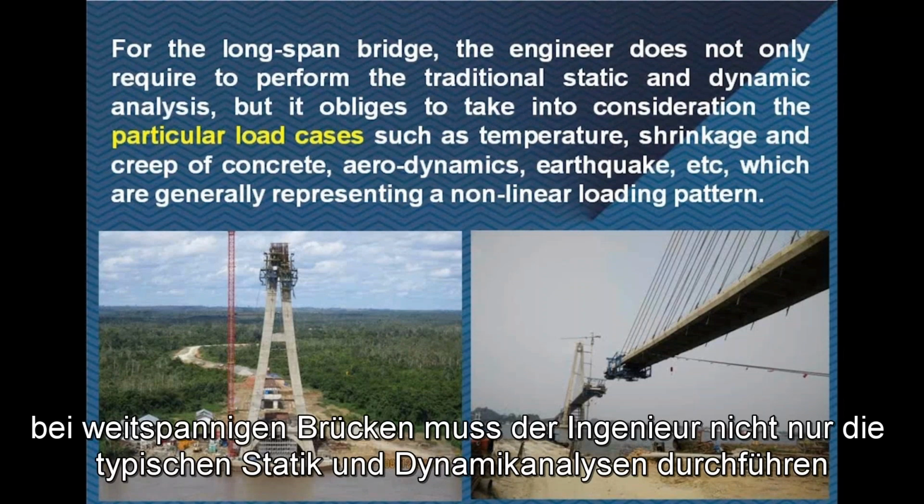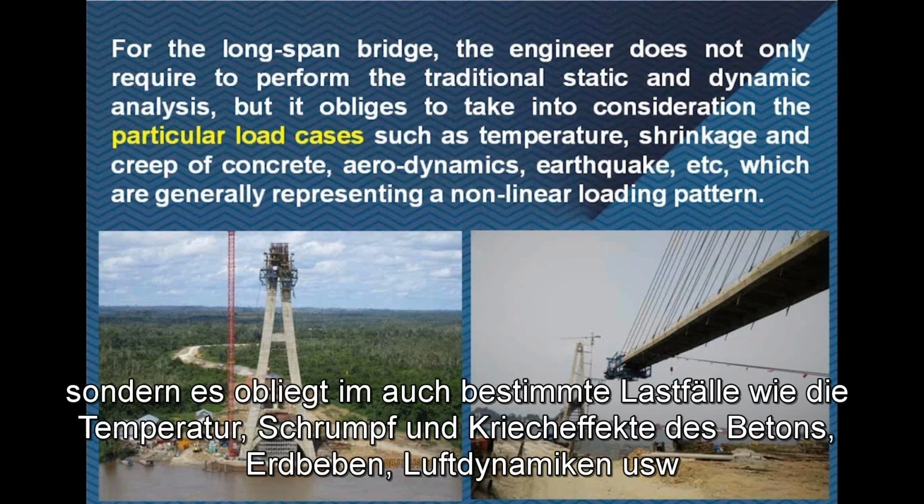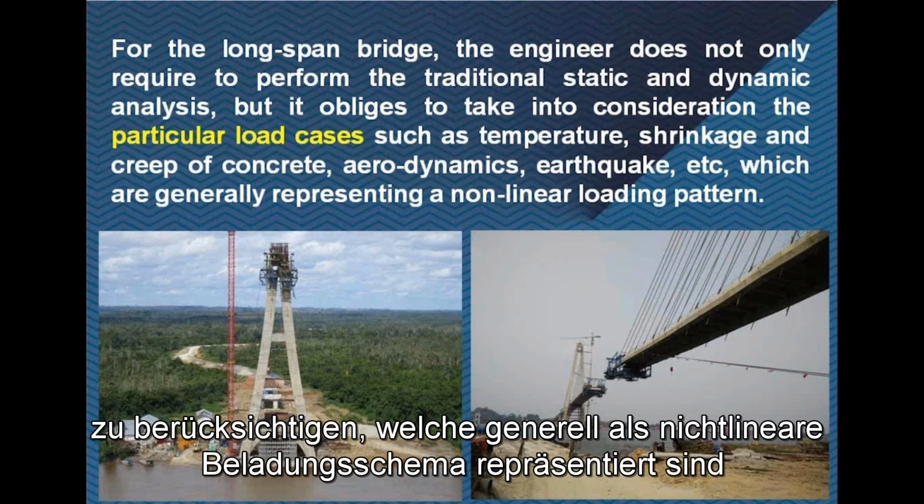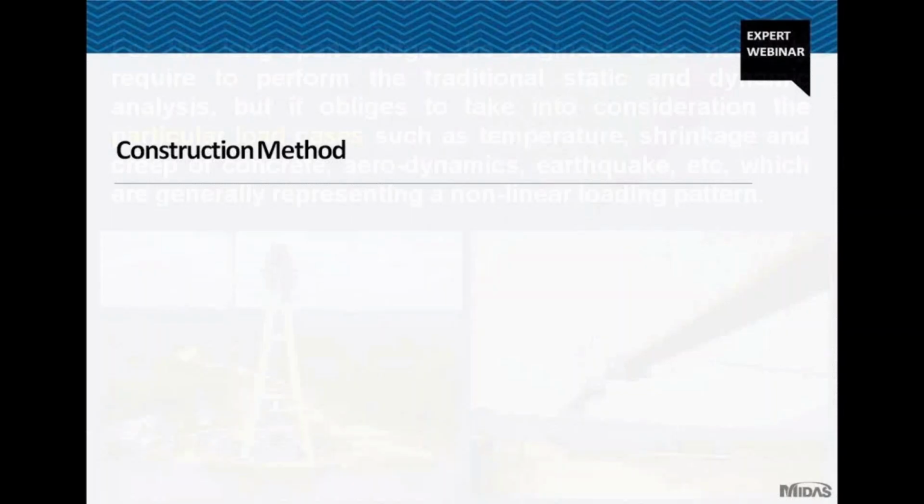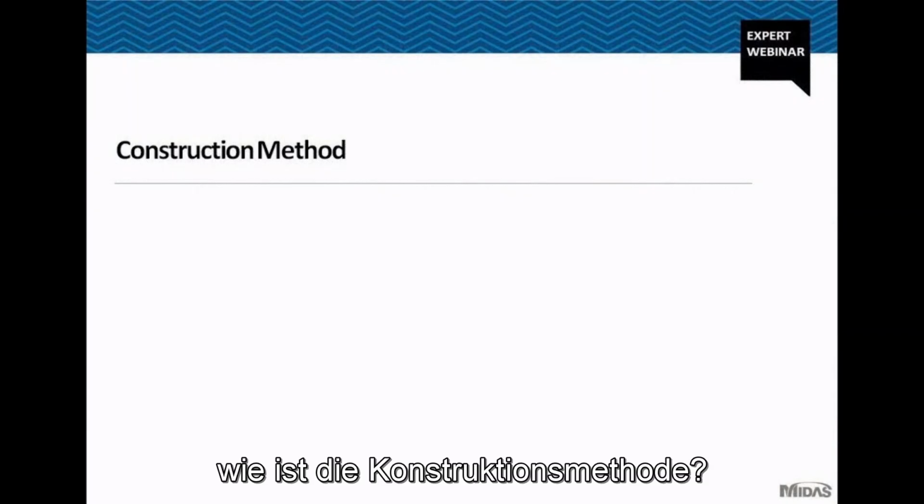For the long span bridge, the engineer doesn't only require performing the transitional static and dynamic analysis, but is obliged to take into consideration particular load cases such as temperature, shrinkage and creep of concrete, aerodynamics, earthquake, etc., which generally represent a non-linear loading pattern. How is the construction method?